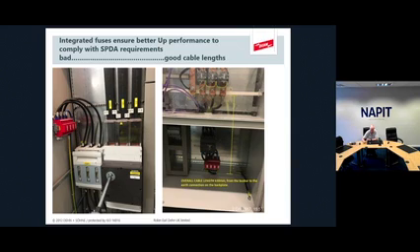In a distribution board or consumer unit, I think you can reach these values in terms of distance, no problem. You've got the neutral bar, you've got the earth bar, you've got an MCB, in this case feeding a Type 2 device, because the regs say 5 kA is all you need in terms of surge value. So a 6 kA or more rated MCB is fine there, but on these larger ones, you do have to watch the actual value of the fusing there.